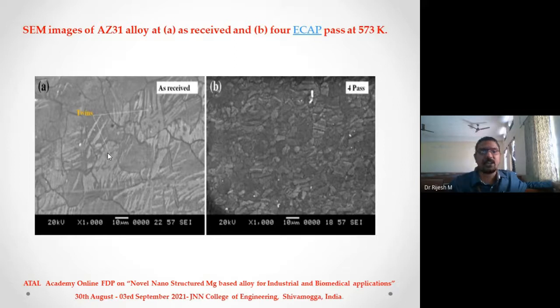And twinning will not happen at higher temperature. Why twinning will not happen at higher temperature is because slip planes become active at a higher temperature, and plastic deformation takes the least resistant path. It takes the least energy. Twinning is dominant at room temperature because some slip systems are not active at room temperature. So twinning becomes easier.